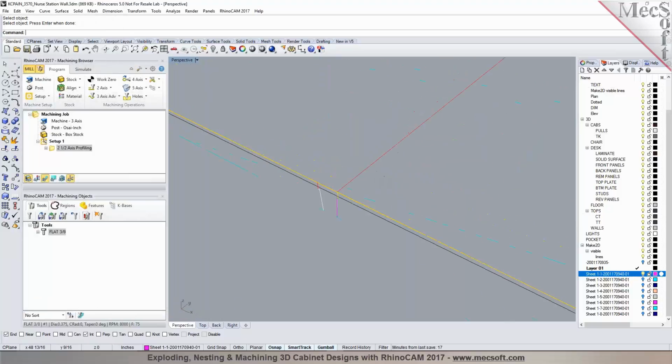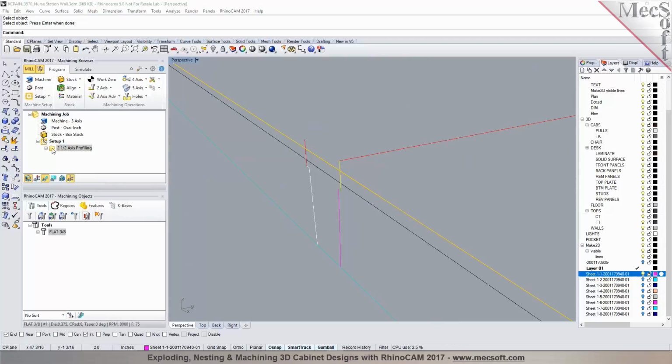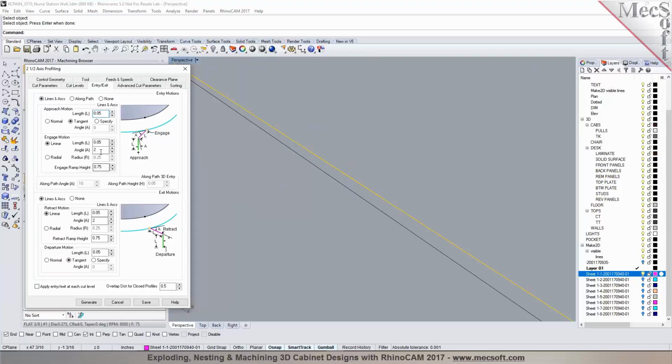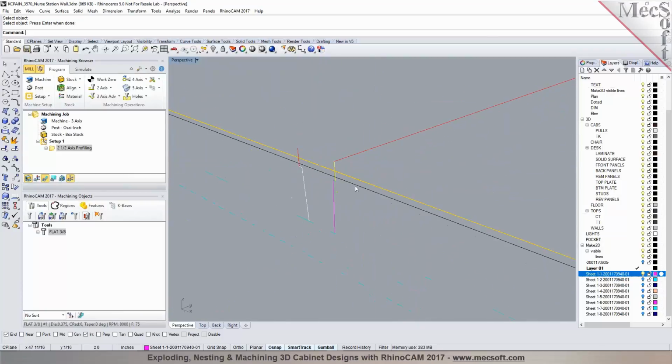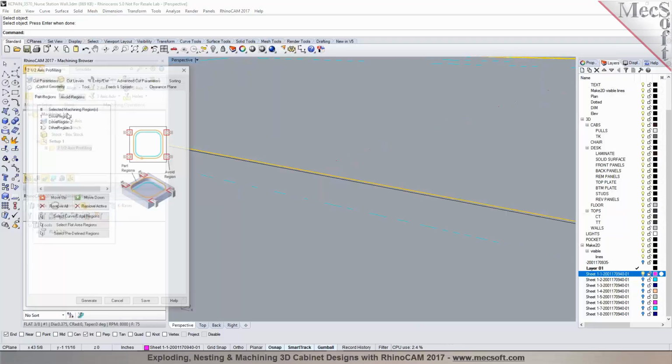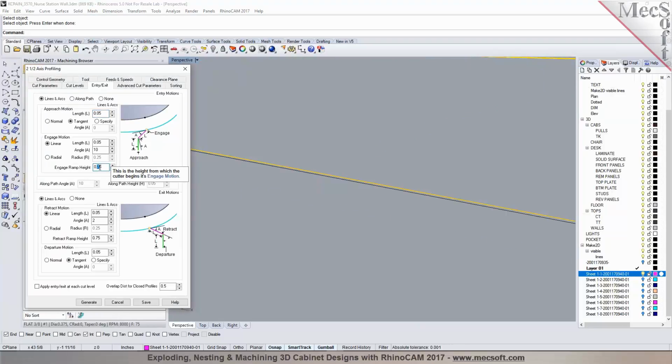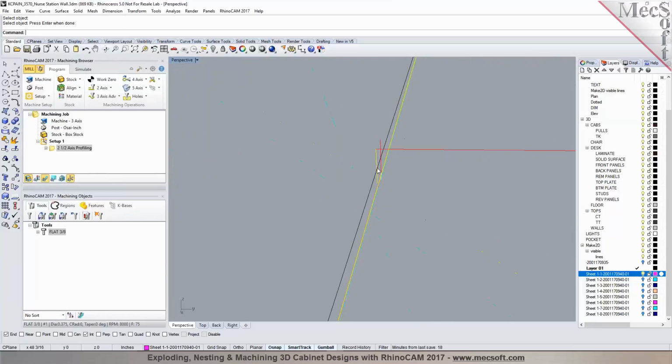So in this process, it's going to process your tool path, and you can see here it's ramping along this curve path as you notice it. It's not just plunging, it's ramping. And I could change the angle in here, or right in here, I could specify it to be like a 10 degree. It's going to ramp along a 10 degree path as you notice it. And it's ramping in here at, the height is set to 3/4. I can lower it down to maybe just 0.15. So it's going to use much more of a gradual ramp as you notice it.